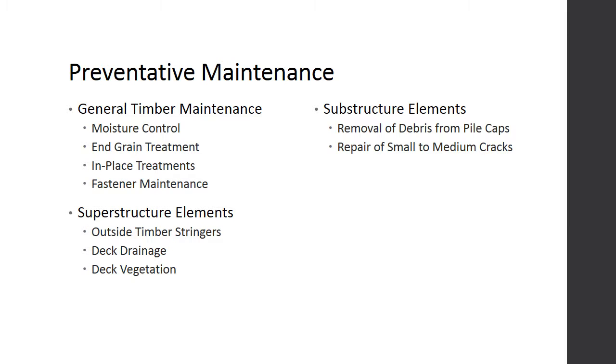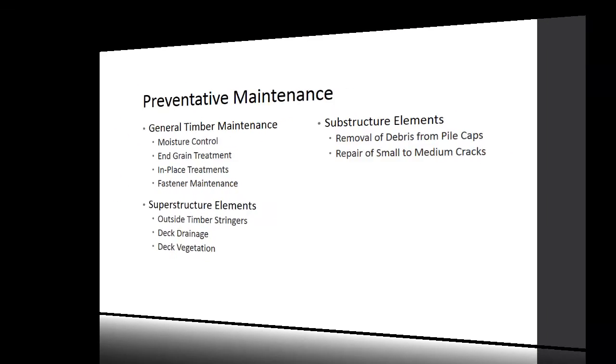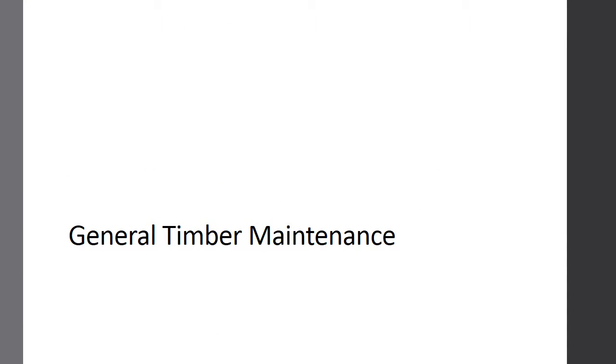With respect to the superstructure, particular attention should be paid to the outside stringers and decks, where exposure to moisture and other elements is most likely. And with respect to the substructure, debris removal and small to medium crack repair are preventative maintenance practices. Each of these areas will be further discussed in the upcoming slides. This section will touch on several general maintenance methods that can help extend the service life of a timber bridge.